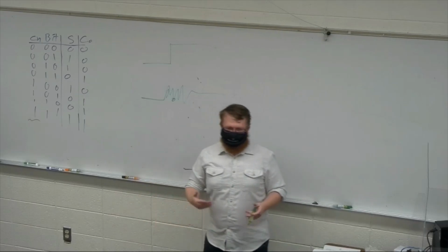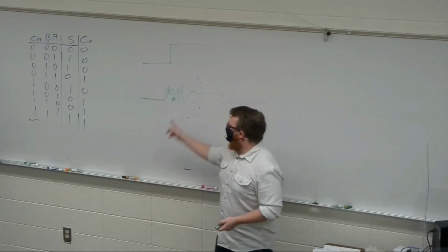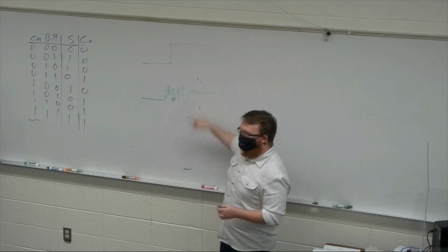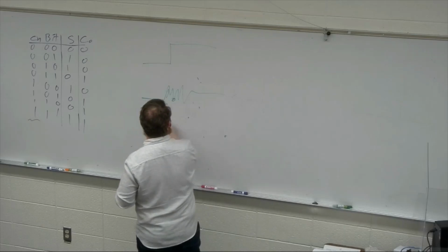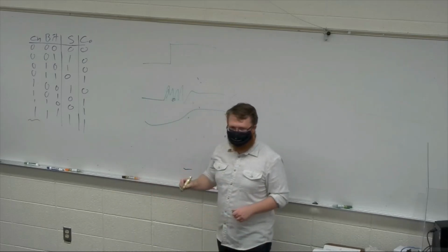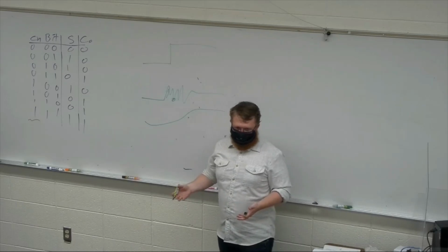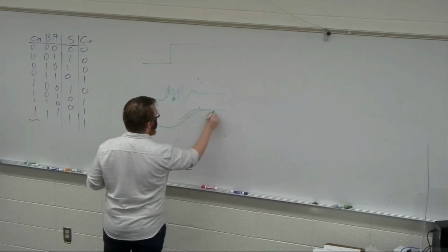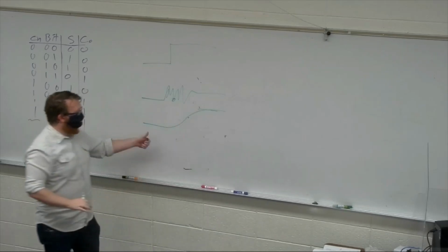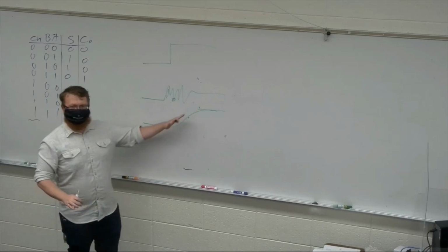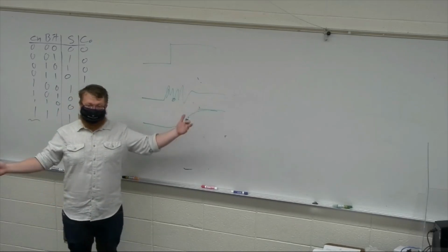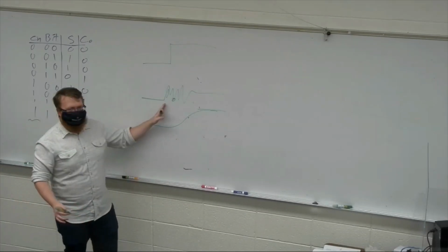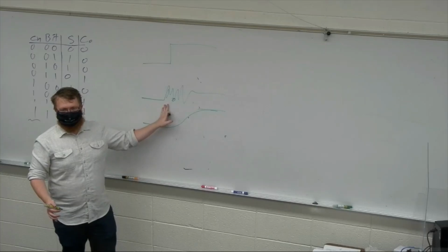So a couple ways of dealing with this. Well, the first one is a hardware solution, right? We could put a filter on this so that it can't just go up and down. You throw the switch and it just kind of wanders up to that level. Sorry, this should just be a flat. Right, so I throw my switch and it has to charge up some RC circuit. The downside is now I have to have an RC circuit, so I've just added size. The other issue is it actually ends up having to be quite a bit slower than your circuit does.